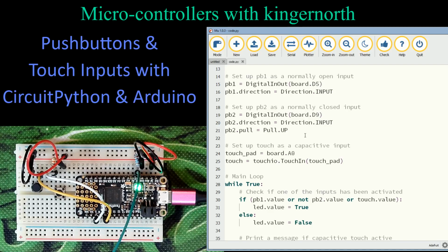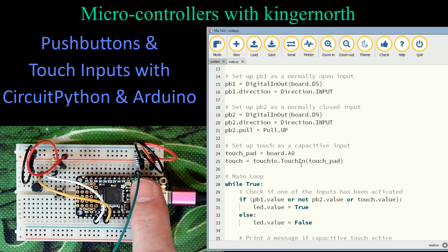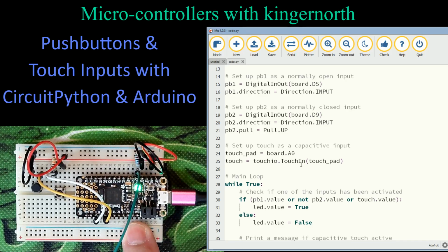And it's wired up slightly different. That's over here, and this is the analog pins back here, on the green wire. I have my 10 million ohm resistor on this particular board. I have it going to common. So I put the 10 million ohm resistor in here because it's not built into the feather.